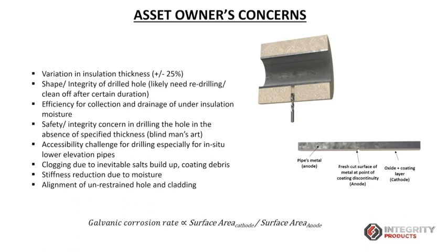If I'm buying insulation from a supplier and I specify that I need 60 millimeter thick insulation, since they are supplying the product within ASTM compliance, they have the flexibility to give me insulation of 48 millimeter to 72 millimeter and claim that it's 60 millimeter.